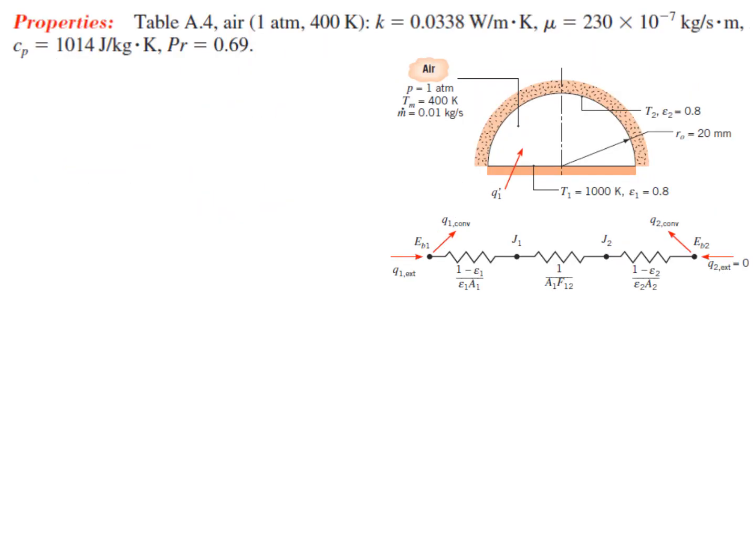So I have to figure out what type of convection heat transfer I have here. I have free convection heat transfer or forced convection heat transfer. I would say that this is forced convection heat transfer because I'm forcing flow inside this duct. So among the forced convection heat transfer options, I have forced convection in external surfaces or internal forced convection.